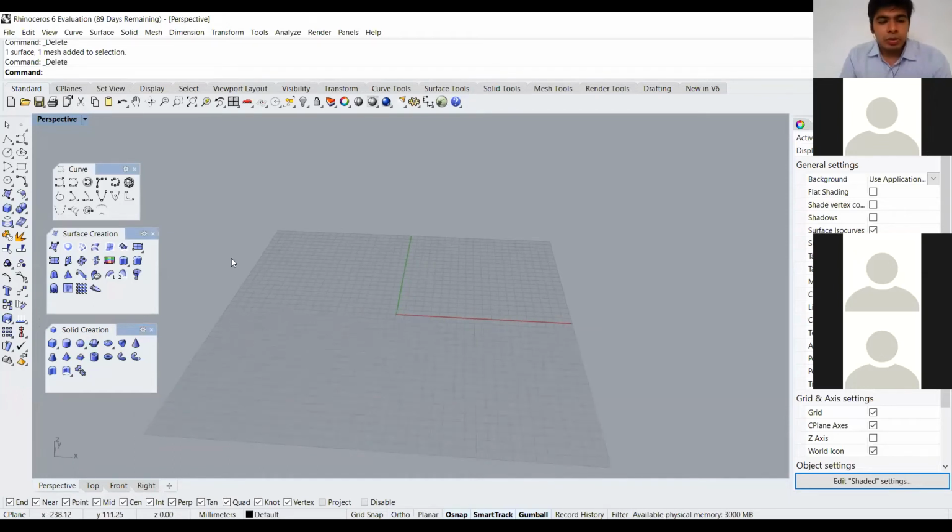Yeah, so what I want you guys to do is take these 3 dialog boxes outside. One is over here at the curve, which is the fourth icon. Cascade it down and then pull it down. Then the surface creation, and then solid creation. We'll be working in these three: curves, surfaces, and solids in the 3 upcoming courses. And for now, I'm just making simple geometry.